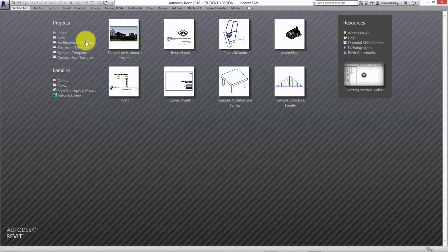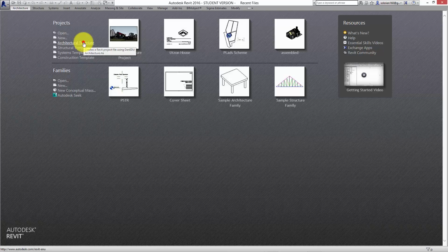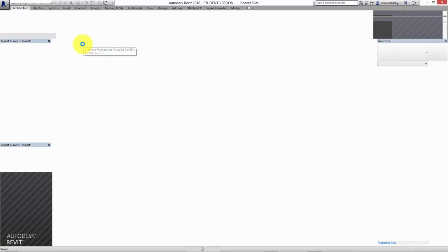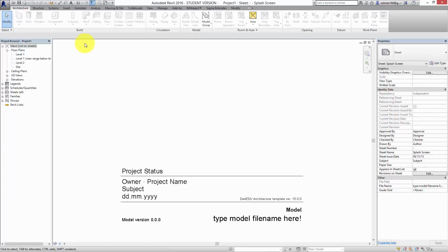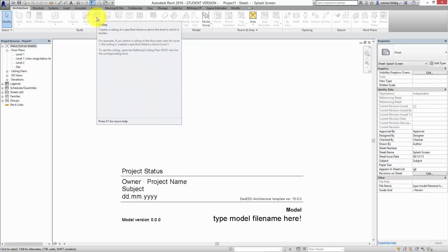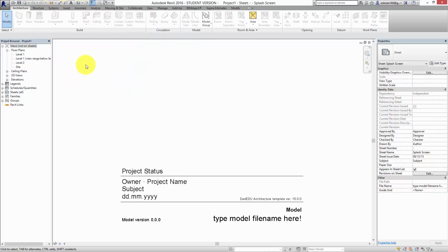Okay, I'm just going to show you a little cheat to make a sunshade, because if you were to make it completely correctly, you would have to make a repetitive family, and you'd have to get into a lot of detail about it. But if we're making a simple sunshade, like a metal structure sunshade, we can use the railing tool to do it, because the sunshade is simply a series of struts that run along, and then a series of rails that run on top of those struts. So it's exactly the same as a railing, it just turned on its side.